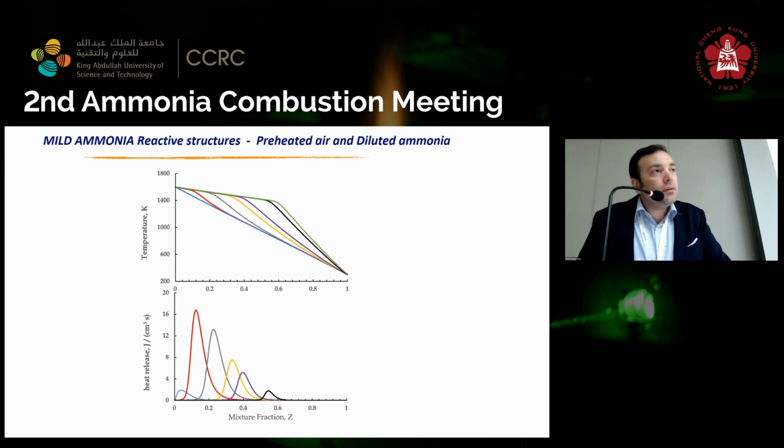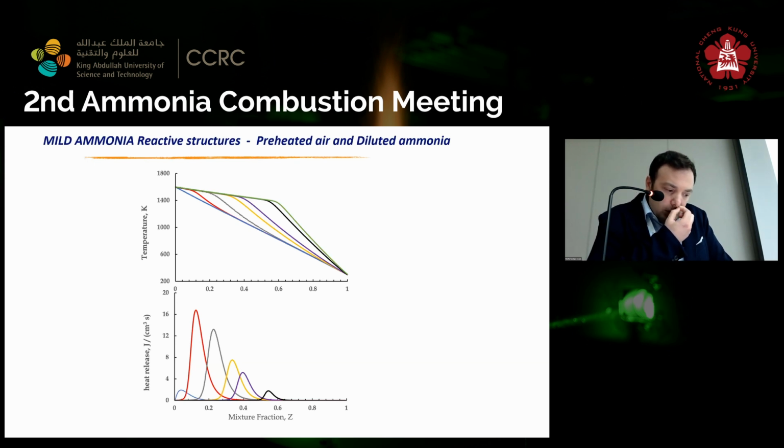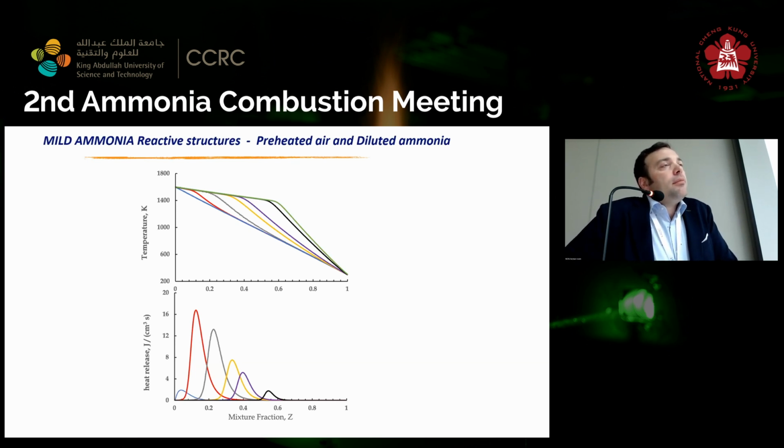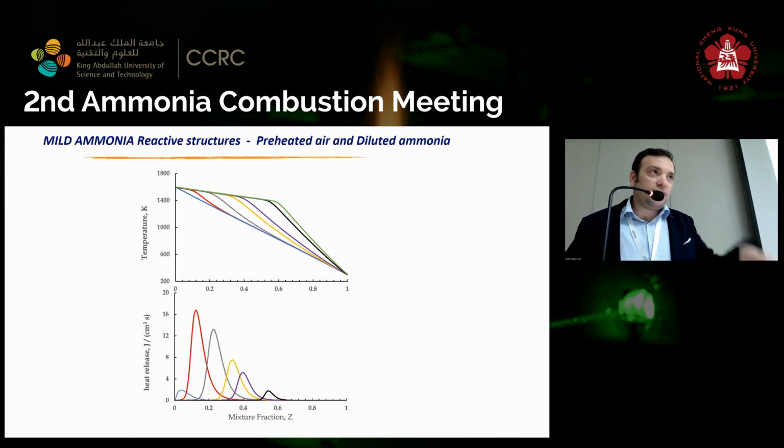As I said at the beginning, I don't think there's any need to call it in a different way. That's all, just semantics, but theoretical definition. You try to concoct a new word like the ignition-diffusion regime, but I don't think that's a necessary definition. Yeah, but the structure that we observed is different with respect to what you call a diffusion regime, a diffusion flame. That's what I'm trying to point out. I don't think so. You can actually use a flamelet solution like that as a steady solution to describe this combustion behavior. If I know the mixture fraction, I can describe all the reactive scalars. Yeah, from my point of view, of the thermochemical state, I agree on that. Yes. I was talking about the reaction structure, which seems to be different.